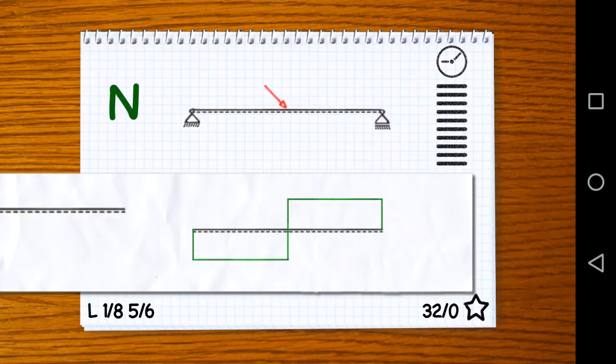I want to say about the different components which ones should be bigger, but let's talk about that another time. We're interested in normal forces here. Now look at this beam. It can be a little bit tricky, but that single inclined load we have in the middle has a horizontal component. So what's going to happen is that the left part of the beam, from the pin support to that single load, is going to be stretched. You can picture that pretty easily, right?